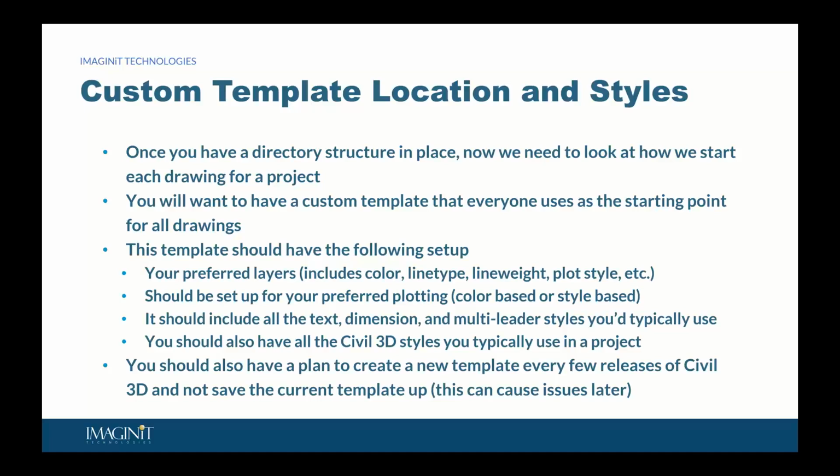Now, if you are a multidiscipline firm, i.e. you have a survey and a landscape architecture and a civil, and you have all three of those disciplines, you may need 3 different starting templates to accommodate that. Anywhere where you can trim the number of templates causes less confusion later on down the road. You'll want to have a custom template, again, everyone uses as the starting point.